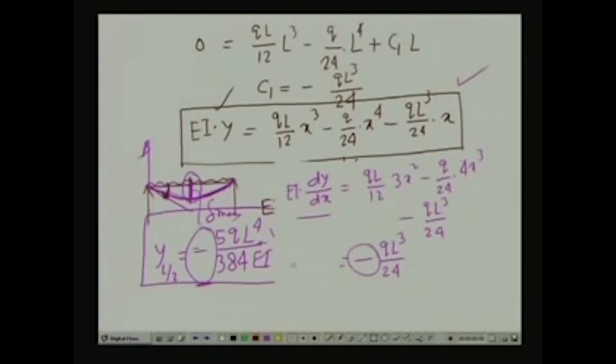Now, as we have seen, in a beam segment the positive bending moment is in an anti-clockwise direction, and consequently, since this is clockwise, we say this theta is negative. Now, if we compute the value of the rotation at the other end at x equals L, then in this particular expression, if we substitute x as L, let us see what we get.